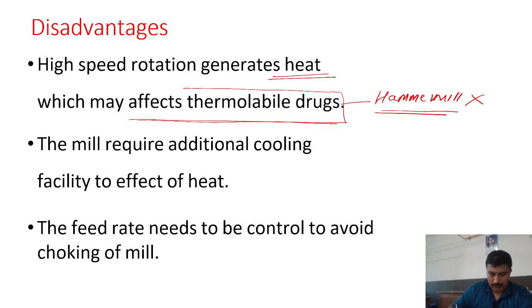If you are using a thermolabile drug, then we require an additional cooling facility in order to maintain the temperature. If you provide the cooling facility, then the effect of heat will not be generated, because the temperature will be maintained at a constant level, and then you can grind the thermolabile drugs. But without a cooling facility, you cannot grind the thermolabile drug, because that may cause degradation.